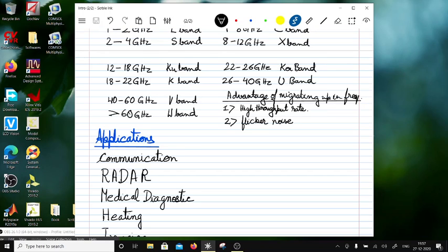These interfaces have defects, or basically places where the carriers can get trapped, and then after a certain relaxation time they get released, right? This causes a certain variation in the charge when a current is flowing. This appears as a noise which is known as flicker noise.